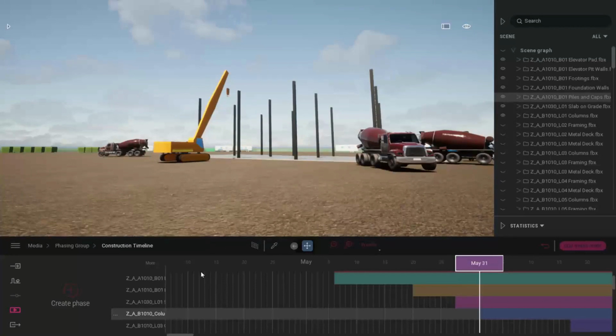Yes. This construction timeline, if we did want to take the time, we can dial it down to the days. One thing Rich and I were playing around with for this presentation: Navisworks has that green transparency that turns on when the construction of an element starts, and then it shows full opacity when it is finished. So at the beginning of the 5 days, it showed as green.